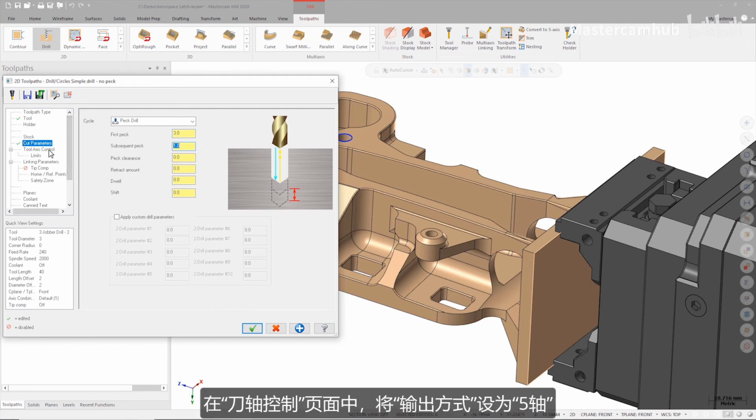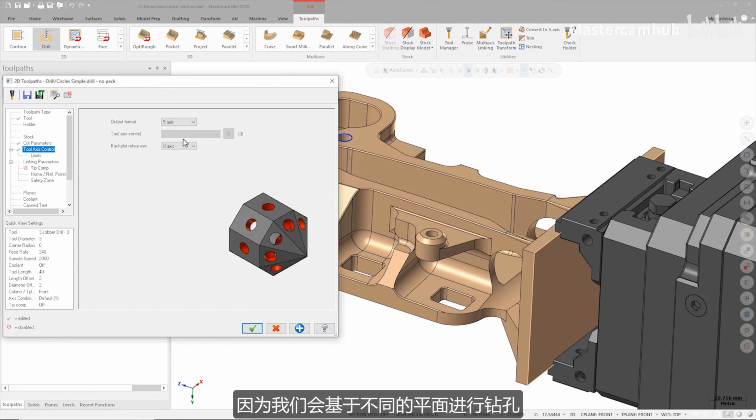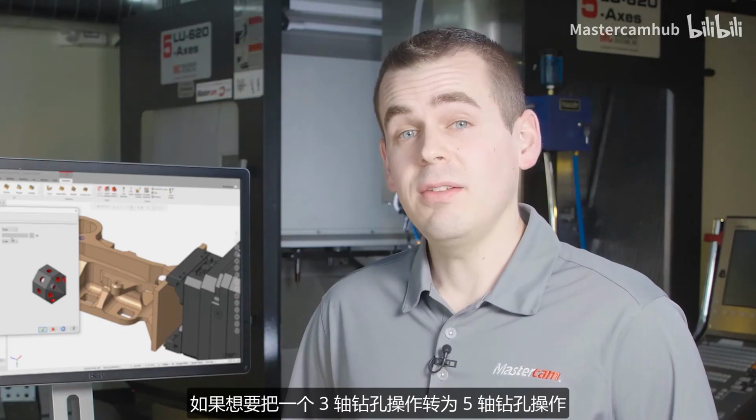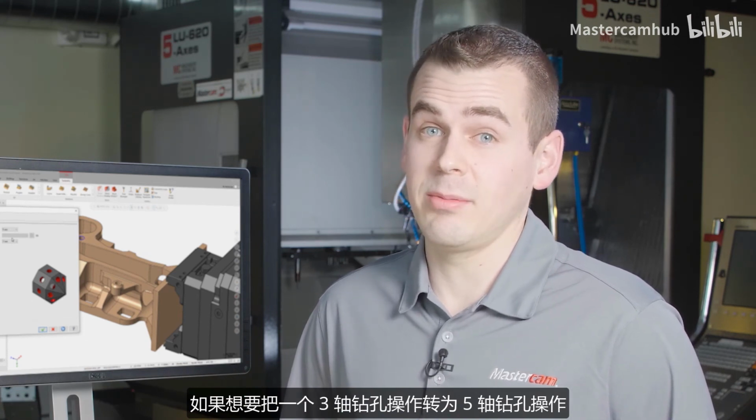On the Tool Axis Control page, I'll set the output format to 5-axis, since the holes need to be drilled from more than one plane. Since I took the time to set the drilling direction for each of my holes when I selected them, I already know what to expect when I select 5-axis as the output format. If this were a 3-axis drilling operation that I wanted to convert to a 5-axis operation, I would want to make sure to review my geometry selections to make sure my drilling directions were correct.